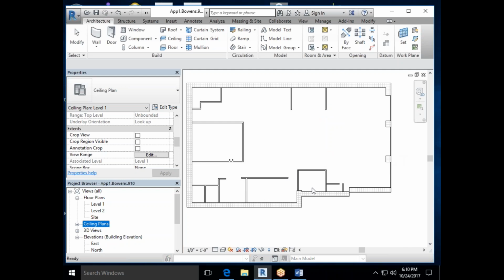Check, check, and check. So you could do all your ceilings on here. Now, I don't think you do 2x2 ceiling tiles for everything though. That's just not normal. It doesn't seem like a good design to me either. It'd be kind of gross to have that everywhere. You'd want to switch between 2x2s and 2x4s and gypsum where it makes sense. Like maybe in the break room is usually where you might just have gypsum. In the bathroom, quite possibly you would have gypsum. In small offices, you could have gypsum unless they need a lot of technology support. And then the rest of the area is where you would have your 2x2s or your 2x4s.